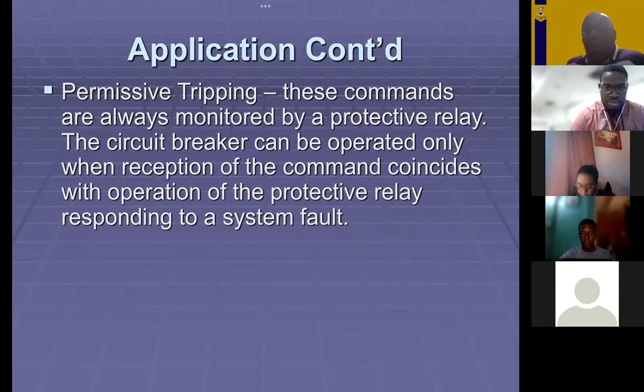Remember we gave two permissive schemes: the permissive underreach and the permissive overreach. And it was just which one of the instantaneous zone settings was used to send the signal.